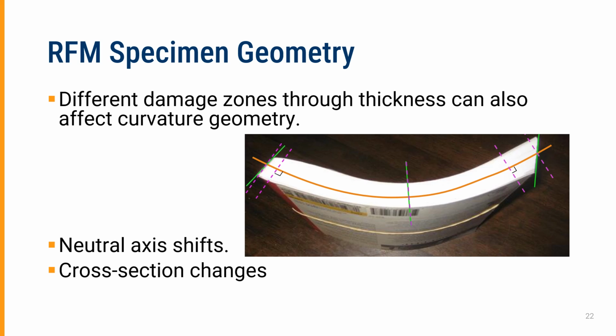But you can see from the previous slide, Timoshenko basically came up with a description that says, hey, wait, the ends actually do not retain their same geometry, and as well, the neutral axis actually shifts as we bend it. So that will affect a couple of things.